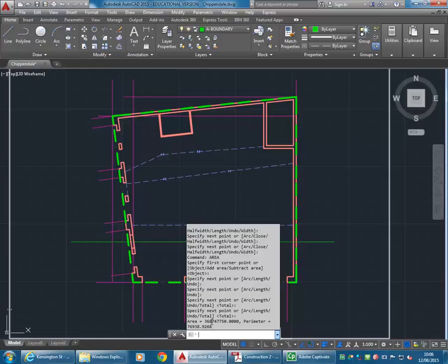But again, it varies. So, like I said, 100 is a good thing to remember, and then 50 or a little bit more for 1 bedroom, because it's roughly 10 or so square metres for a bedroom, and then you have all the circulation space and the other things you need, bathrooms and other things. So then, again, looking at this area here, you could see, just by visually assessing it, that you could fit maybe 3 units in that area, 3 or 4 maybe, and so you can probably tell just by looking at it, it should be around 300 square metres.